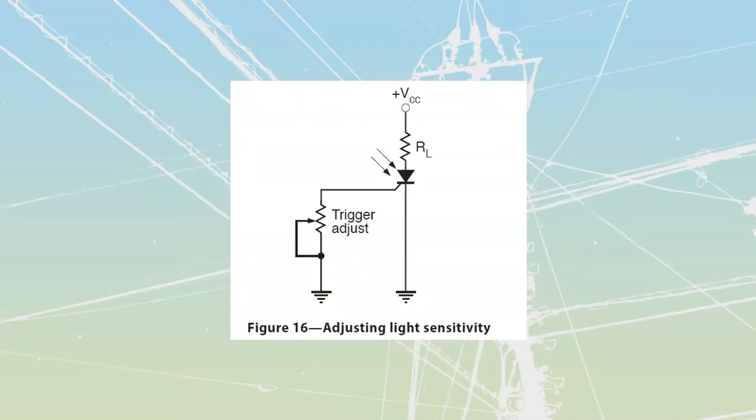In some cases you can adjust the sensitivity of these things. Remember that I said the thing that sees the light inside of there is going to be a photocell, or what we often refer to as PV. Photovoltaics is what PV is short for. The photovoltaics generate voltage. Now I can allow that voltage to drive into my gate to turn this thing on.